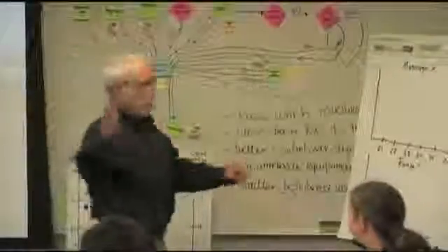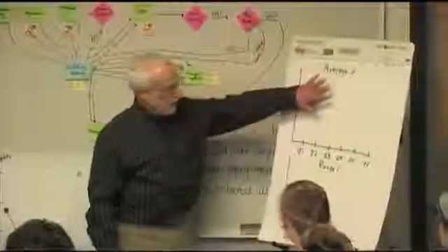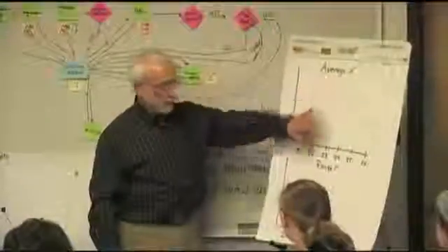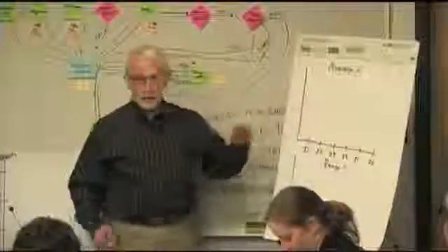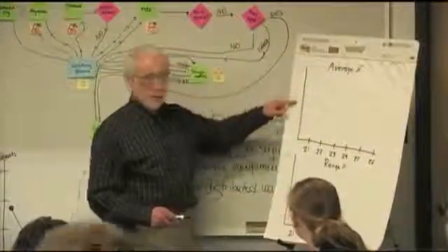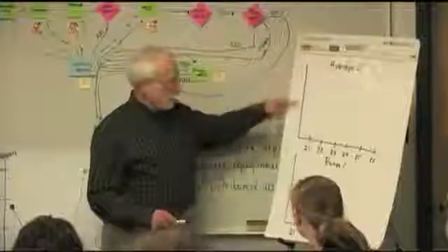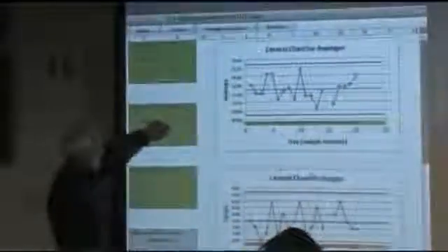Okay, so while we're getting some help here, each of the stations on their easel has a chart for the average and the range. What I want you to do is come put a scale on this where you're going to put the upper control limits. We don't have to be accurate to the second decimal place here. It's about 75.4 and 69.5.